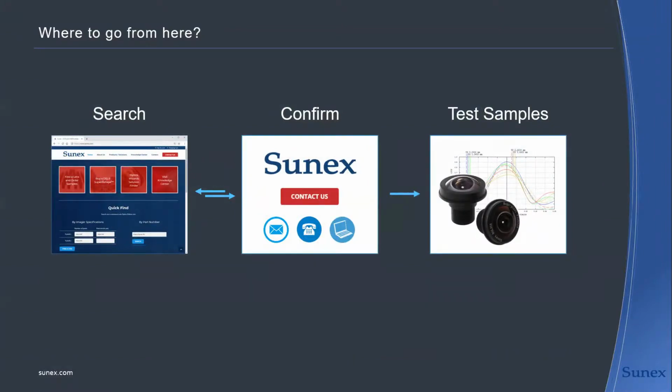If you can start off with maybe even two or three different off-the-shelf lenses, where you pick one lens to investigate very good stray light performance, and another that is more beneficial to your field of view, those tests on your side are very informative for us. You say, I really like the stray light performance of lens A, and the MTF performance of lens B. Can we build a custom design that brings those two worlds together? That's a really important guideline for us, so that we know what to design for.